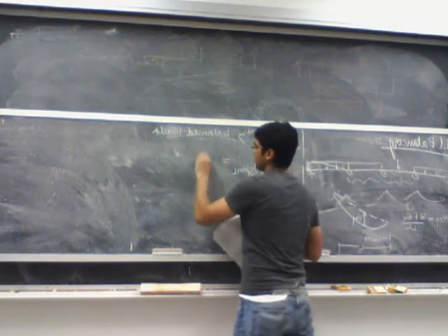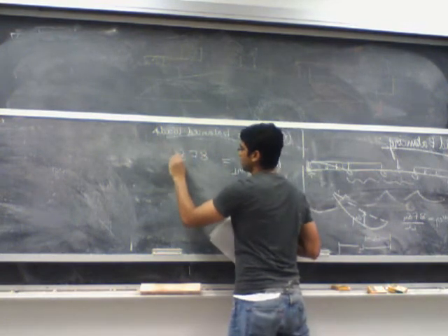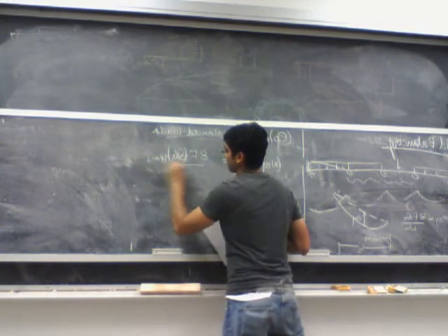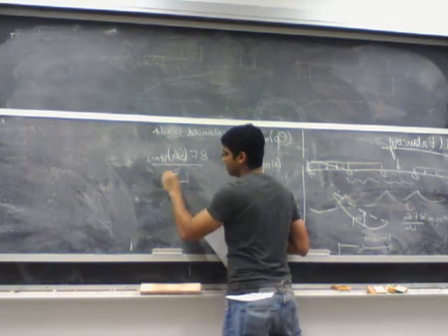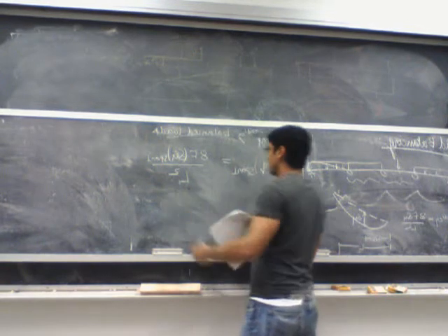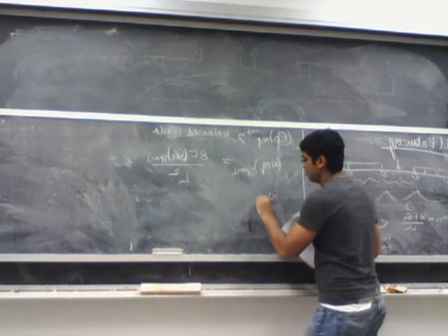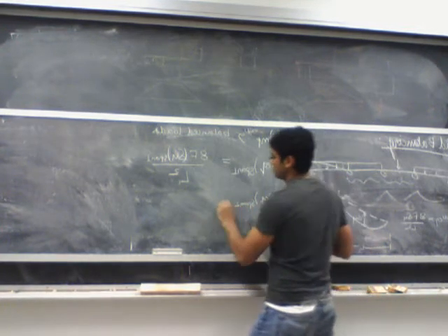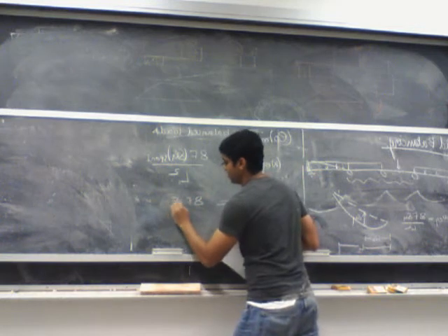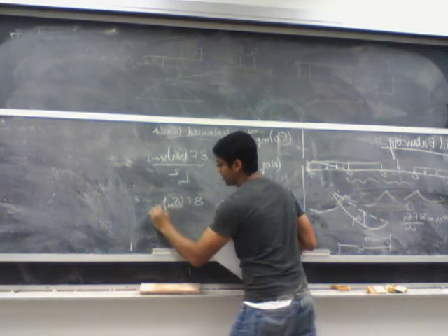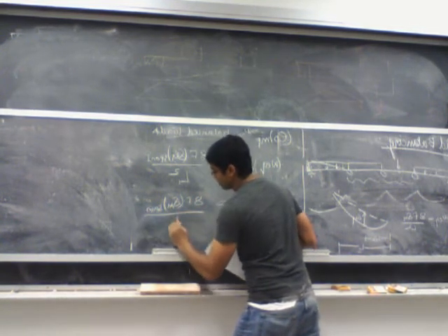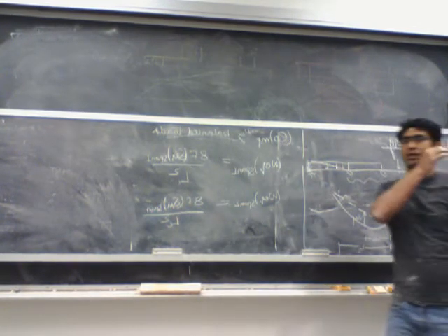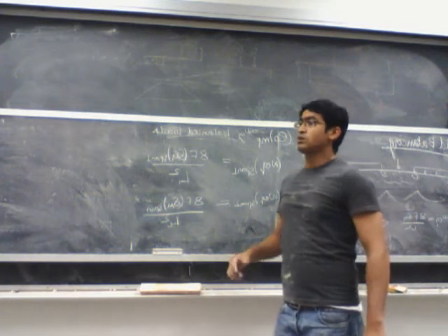This is equal to 8F delta M of span 1 over L1 square. I am saying L1 because it's the length of span 1. Similarly, I can write omega equivalent of span 2 is equal to 8F delta M of span 2 over L2 square, and so on and so forth for each one of the spans individually. Now what?